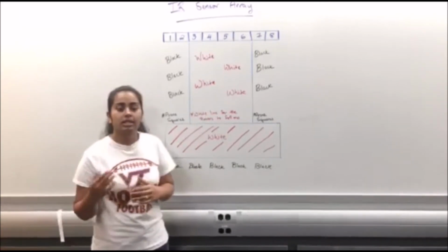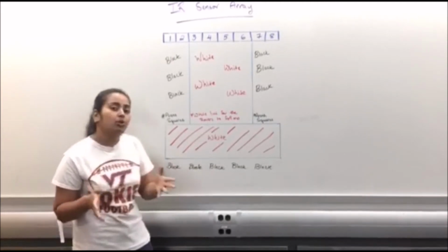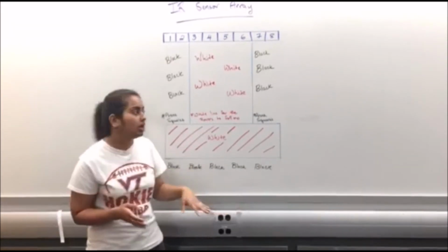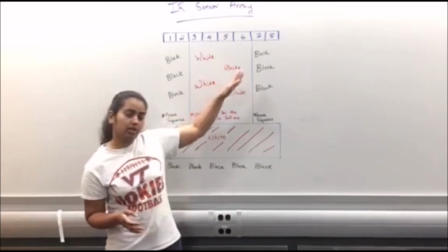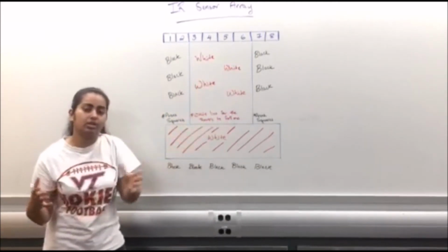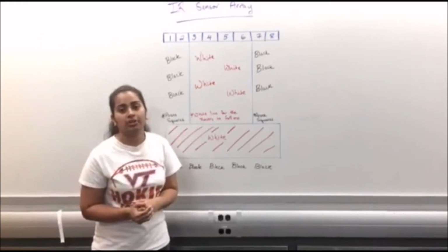The times that the sensor thread sends commands to the motor thread is when it's seeing a forward, left adjust, or right adjust. So if one of these sensors starts seeing white, 7 or 2, it's considered as either left or right adjust, and it sends the appropriate command to the motor thread.